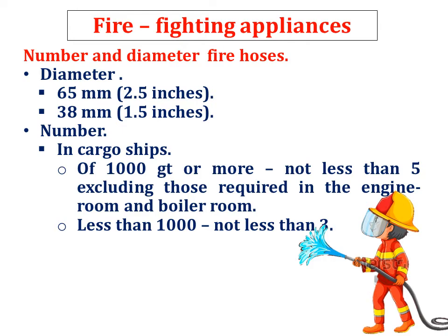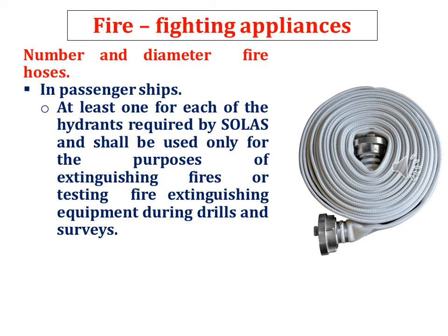Number and diameter of fire hoses. In passenger ships, at least one for each of the hydrants required by SOLAS, and shall be used only for the purposes of extinguishing fires or testing fire-extinguishing equipment during drills and surveys.